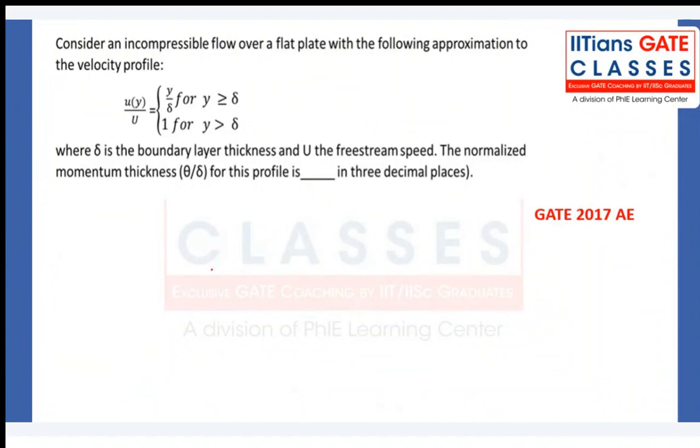The normalized theta by delta they are asking. Very simple. Theta will be the integral from 0 to delta of u by u infinity into 1 minus u by u infinity dy, plus the integral from delta to infinity.